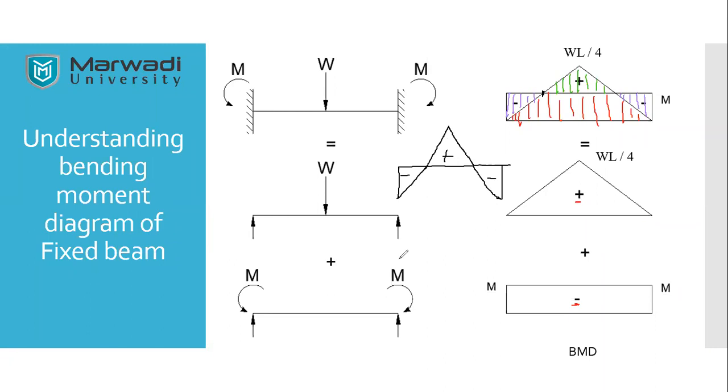The question that somebody asked me in the previous lecture was why the shape of this is a rectangle. Now I guess all of you are clear, because if the load is symmetric, then what happens? Both the supports will have the same moment. This I will write with suffix AB, and this with suffix BA. If both of these are the same, then the diagram is always going to be a rectangle.